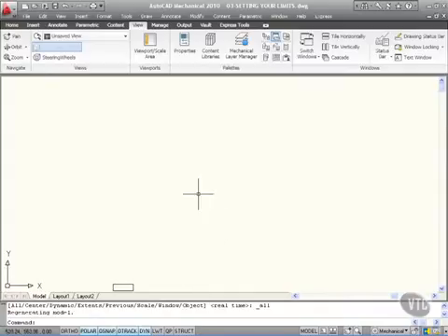What I've done there is I've closed down my infinite space to a bounded space that is bounded by those limits that I typed in. So the bottom left corner of my limits is the bottom left corner of my rectangle at 200, 200. If you look at my coordinate readout bottom left, I'm roughly at 200, 200. If I go right up here, as I come up to the top, I'm nearly at 1000, 1000. Not far off. Let me move a little bit more to the right. That's the other corner of my limits where my crosshair is, ballpark. I can never get it exact because AutoCAD is too accurate.